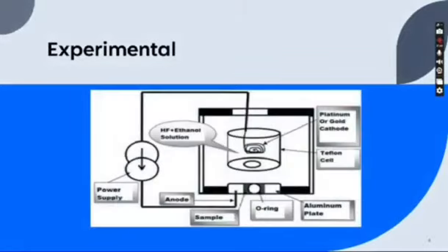Experimental. Preparation of porous silicon samples. The porous silicon films were obtained by electrochemical etching, following a well-defined protocol. The cleaned silicon wafers were immersed in a Teflon cell containing 50 ml of etching electrolyte prepared by mixing hydrofluoric acid solution 40% and C2H5OH 98% in a volume ratio. The ethanol solution was used to obtain a uniform porous layer and to minimize the formation of hydrogen bubbles on the surface, thereby homogenizing the porous layer.